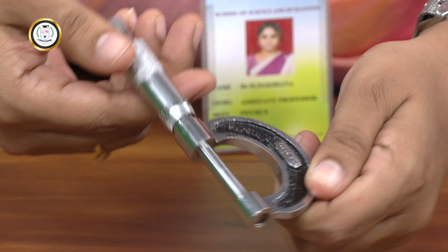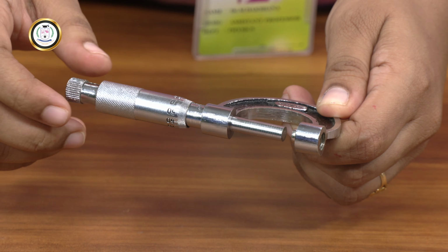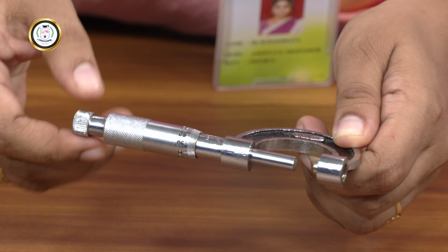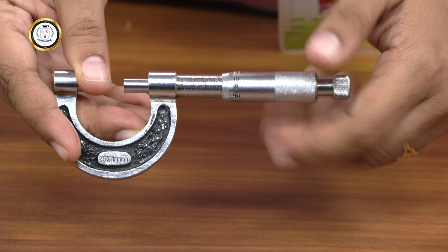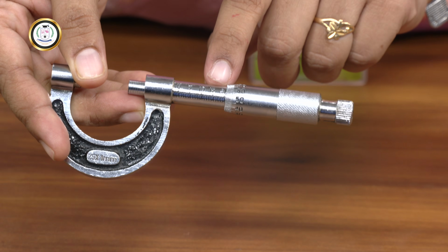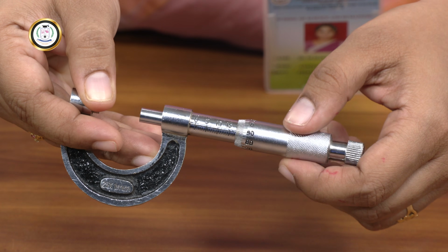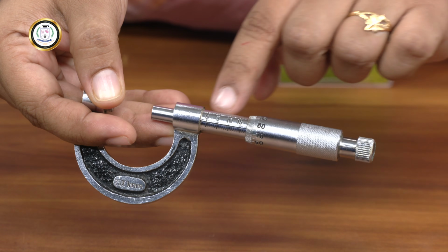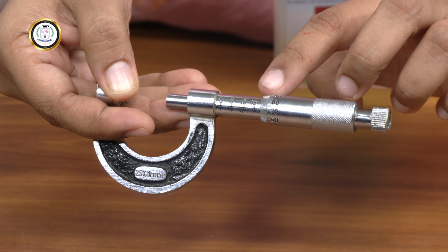So as you can see, this is a screw gauge. Using the screw gauge we can measure the radius of the wire. Before going to the measurement, we are supposed to calculate the zero error and zero correction. When you open a screw gauge, you can see there are divisions inside this screw. As you can see now, this scale which you have here is called a pitch scale. It has divisions from 0 to 25, and the screw which you are rotating here also carries a division. It starts from 0 until 100, and this is called your head scale. So the scale which is inside is called your pitch scale, and the scale which is in the topmost layer is called a head scale reading.